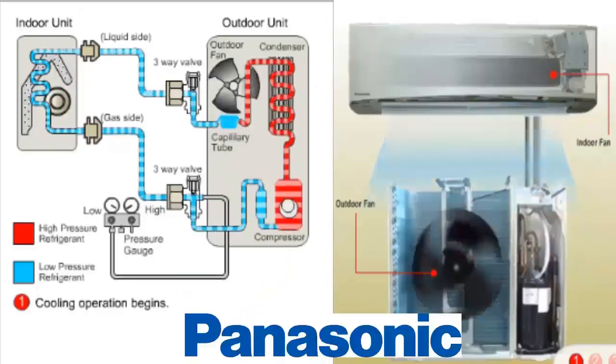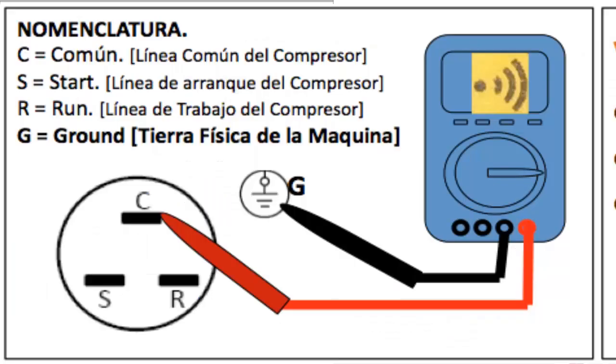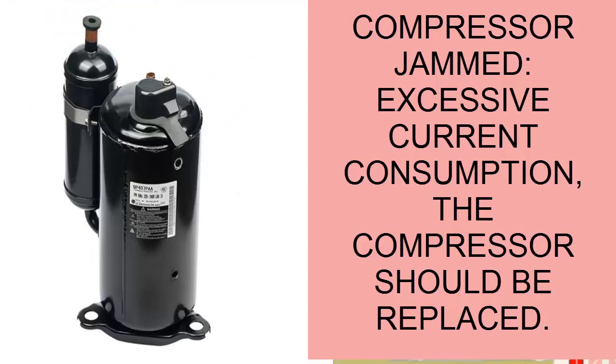When measuring the pins of the compressor's connection with respect to the housing, they should be completely isolated, meaning they should have infinite electrical resistance. C. Mechanical issues with the compressor, making it impossible for the motor to turn the compressor, due to a blockage.